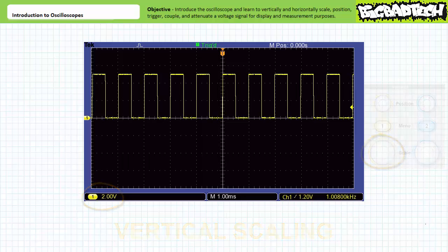Note the pulses appear to increase in magnitude, however this is an illusion only, since each vertical division is now worth only 2 volts per division. Given this increased level of vertical magnification of the same 5 volt pulses, each pulse takes up 2.5 divisions at 2 volts per division rather than 1 division at 5 volts per division as previously. Absolutely nothing about the test waveform has changed, only we've zoomed in a little bit.